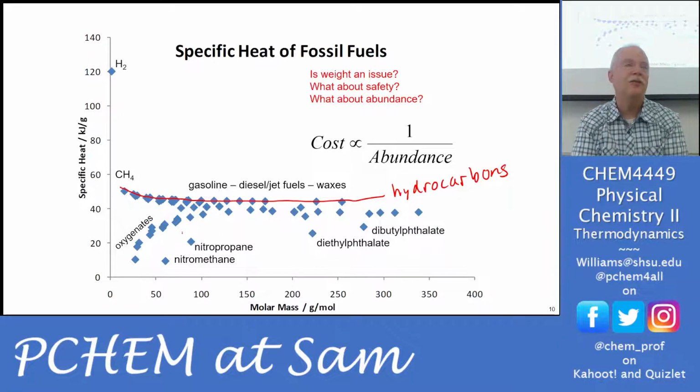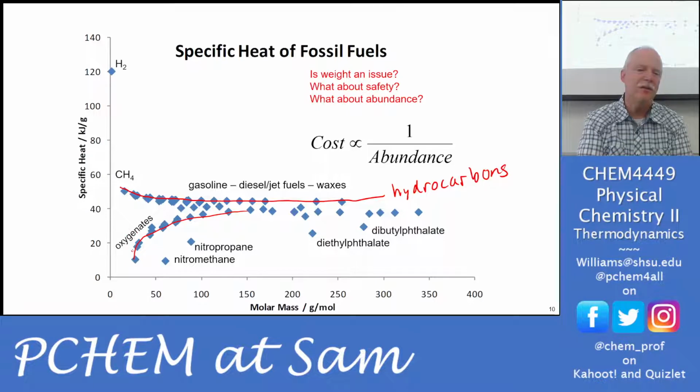You say, well, you put nitro in there, it's like boosting car engines and so on by putting nitrous oxide and so on. Yeah, those actually don't give you more heat because of the nitro compounds. They're giving you more oxygen. So it's a way to put oxygen into the cylinder in like a liquid phase rather than a gas phase. So it's a way to stuff more oxygen in the cylinder. They're not actually giving you as much energy as the fuel is. Okay, but they're giving you more oxygen. But then the other oxygenates blended in, these are already reacted with the carbons. So like the alcohols and so on. So these will be alcohols and ketones. So OHs.